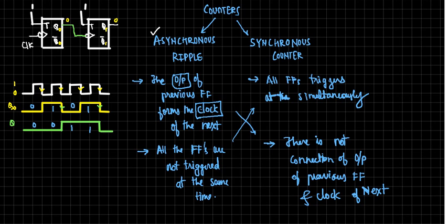Can you see the pattern? This is Q1, and so it is Q1 and Q0. They are taking the states as 0 0, then 0 1, 1 0, 1 1. Isn't that a counting which is happening? This kind of structure is taking some predefined sequence or predefined states. Of course, it's a counter. All the states are not changing at the same time.